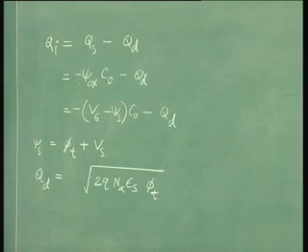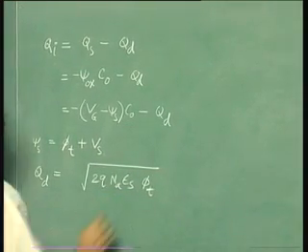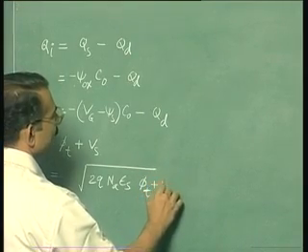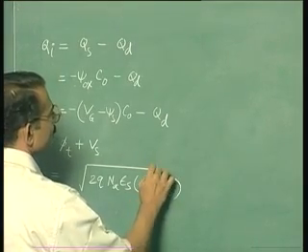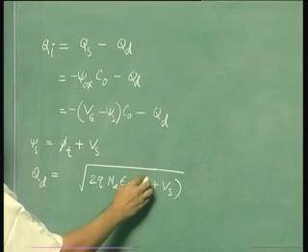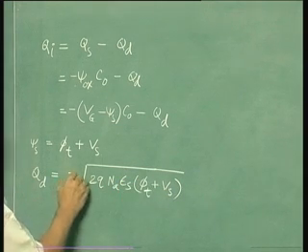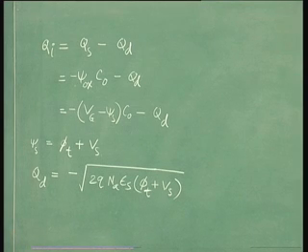This was when it was a two terminal capacitor and it was in inversion. Now all that you need to do is replace phi t by phi t plus Vs, because this is the new value of psi s. This phi t is nothing but actually psi s. Of course you should have a negative sign here, because the charge is negative in polarity.